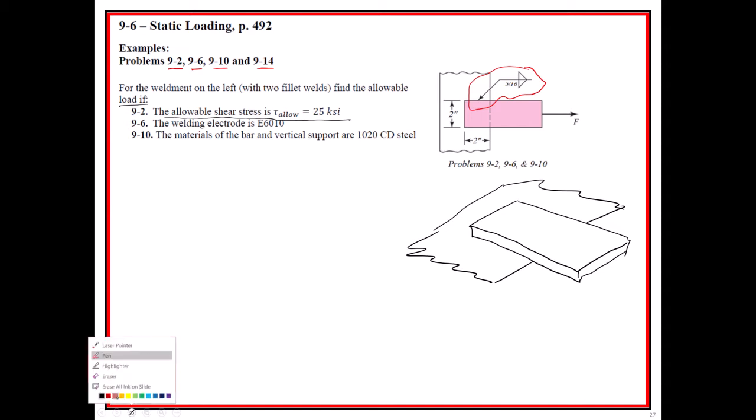And so we're applying a force right onto here, F, and the weld is going to be 5/16 high, and it's going to be a fillet right here. So right there to right here, and if we were to look, that height is 5/16. And I'll draw the rest of the weld right there.